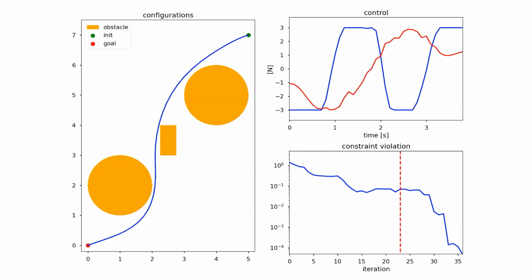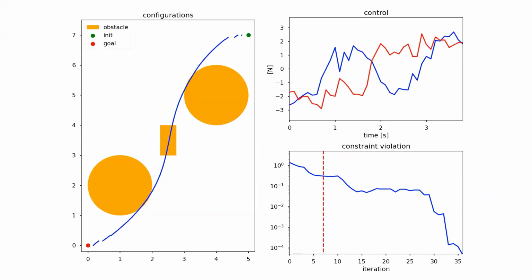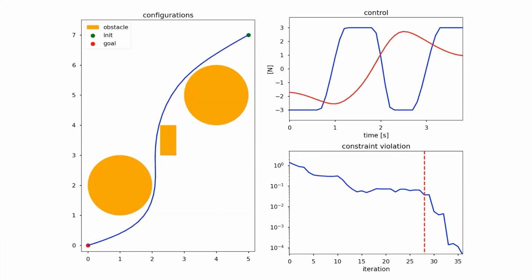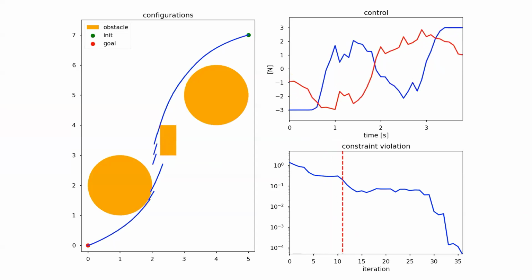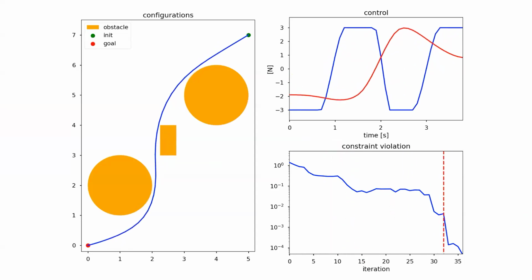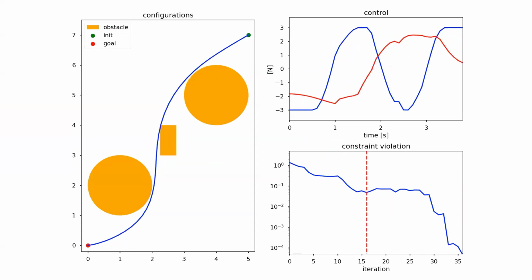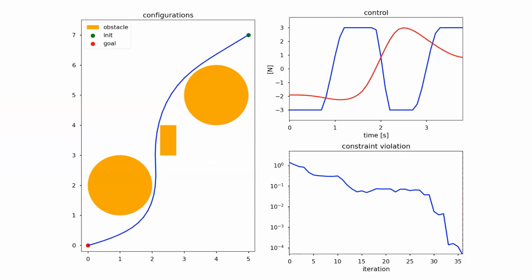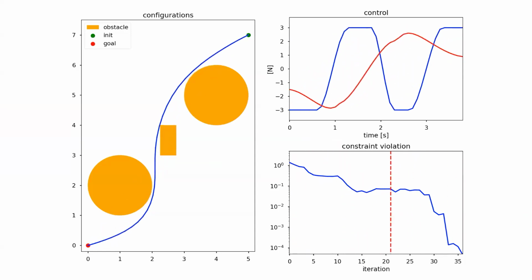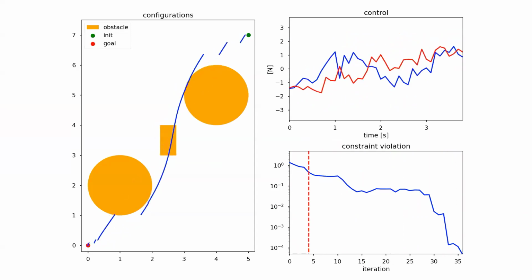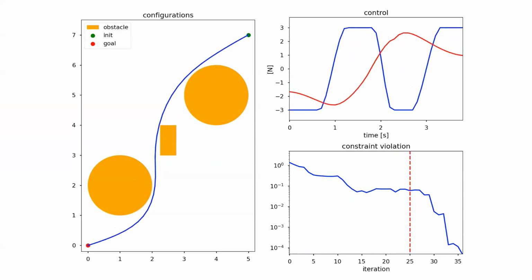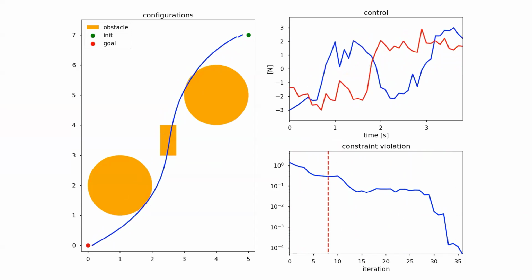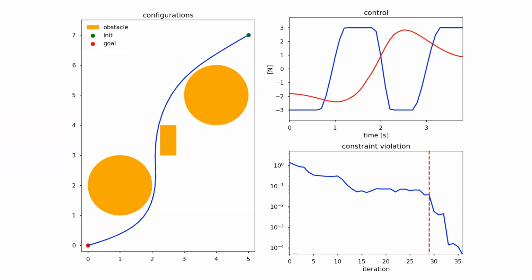And then we mentioned that we have these arbitrary nonlinear constraints C, and this can include anything. And I made no assumption of differentiability of that as well. So here I use some collision keep out constraints. I say here's 3 convex obstacles, and I must keep a double integrator that starts at the top right and ends at the origin. And I must keep our robot, whatever it is, away from these obstacles. These constraints are all non-convex and non-differentiable in this case.